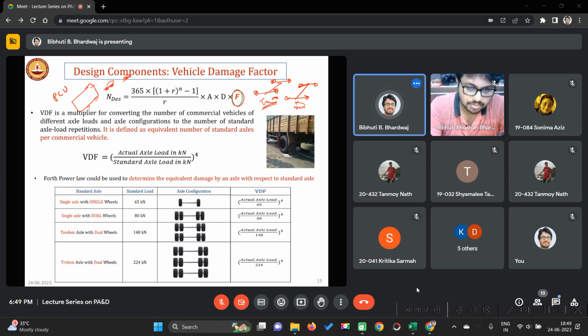So we convert to PCU. A simple Maruti 800 or Alto car is considered as one, and in comparison to that, we convert. The truck will have 4 or 5 PCU, a cycle 0.4, a bike 0.5, like that. So here also we need to convert.